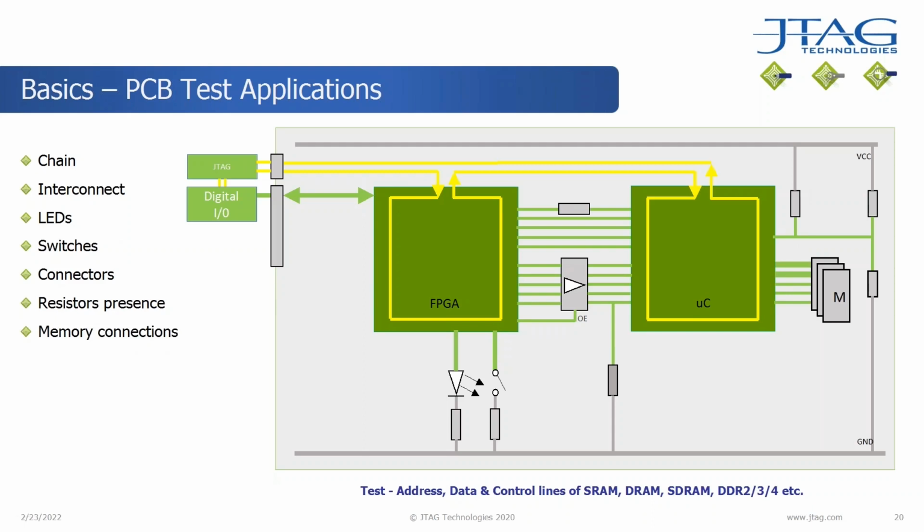For some special devices like memories, we can create tests which allow you to write to the memory, read back from the memory, and using a selected number of test patterns, so we don't have to write to every memory location, we can detect any shorts or opens on the address and data and control signals. So we just use a small number of carefully selected patterns to do that, and that means we can test quite large memory devices, dynamic memories, DDR memories, DDR3, DDR4 even, in fact. So quite a lot of scope there for testing that type of part.